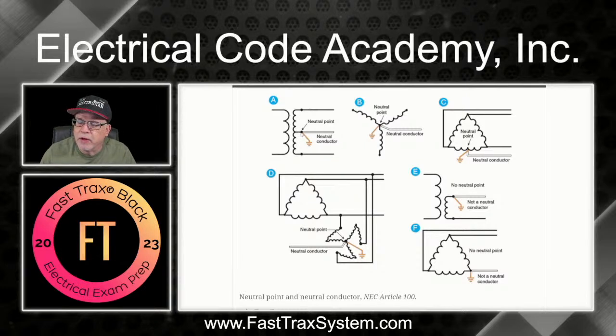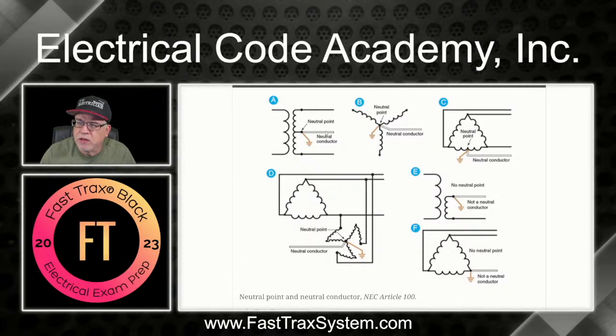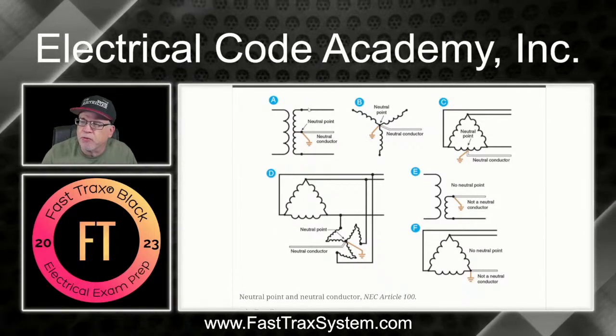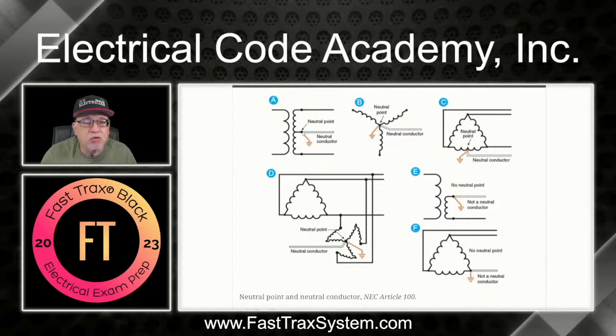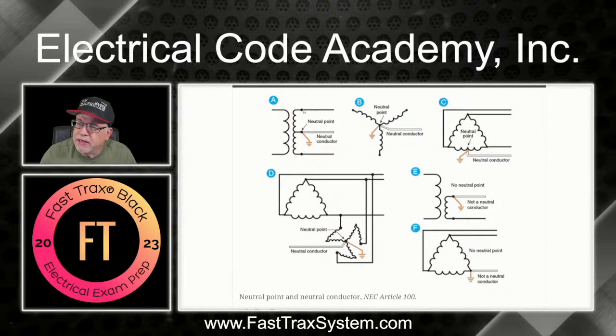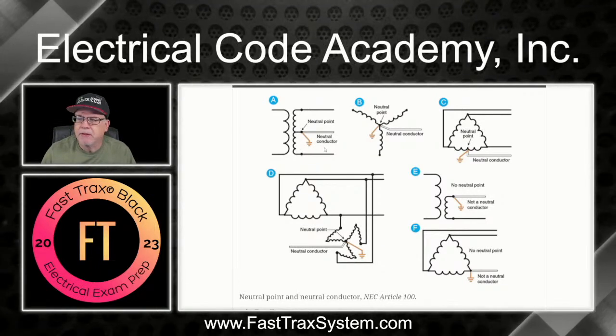This is the neutral point, and that is where the neutral conductor connects. That's why the informational note was important for the reference. From here to here, it's 120. From here to here, it's 120. From here to here, it would be 240. This is the neutral point between the windings.